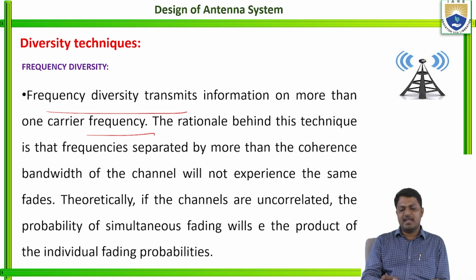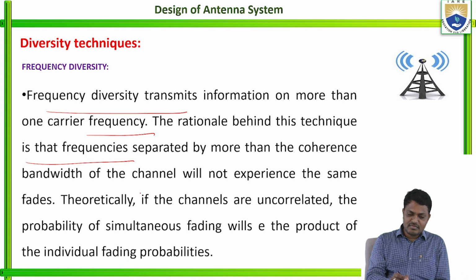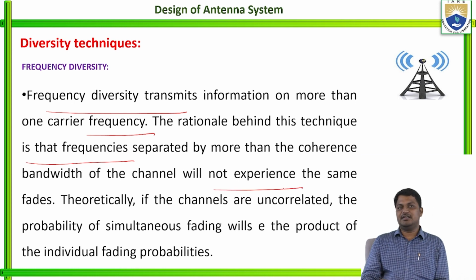The rationale behind this technique is that frequencies separated by more than one coherence bandwidth of the channel will not experience the same fades. Theoretically, if the channels are uncorrelated, the probability of simultaneous fading will be the product of the individual fading probabilities.